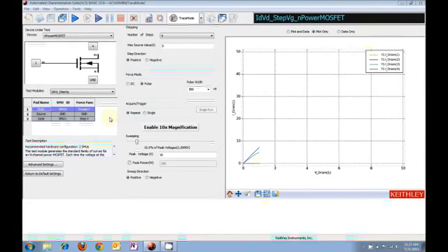Here is the trace mode interface of the parametric curve tracer. Just like on a traditional curve tracer, there are controls to set up the step source, a graph to view the collected data, and a sweep slider to adjust the output level, similar to the knob found on a traditional curve tracer. One benefit of trace mode over a traditional curve tracer is that trace mode has device libraries that set up the test for you.